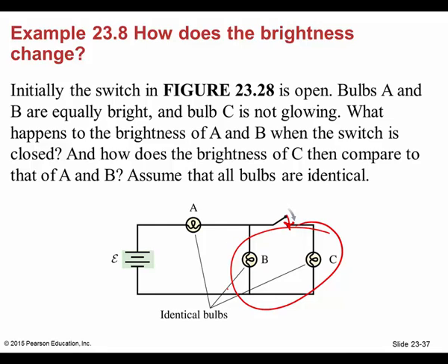And so what you have to do is you have to realize that these 2 are in parallel, and then they form 1, which is in series with A, okay? And so you just have to be methodical, and when we work some problems, I'll show you what I'm talking about on these circuits, how we reduce these down, okay? All right, I'll show you how to do that.